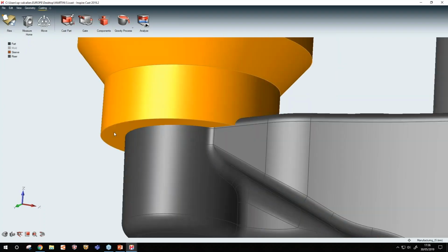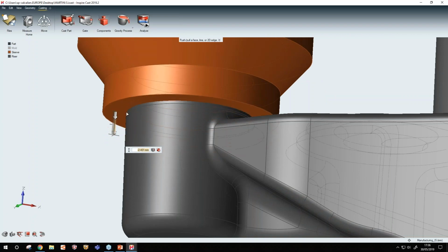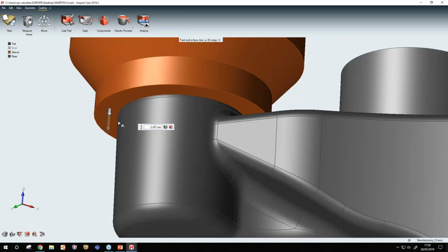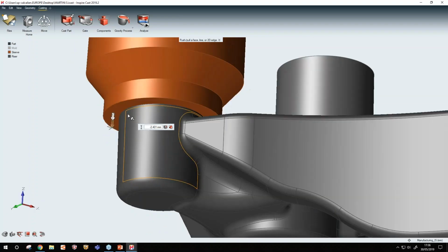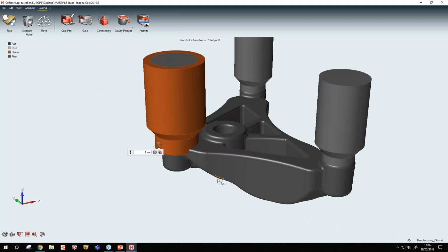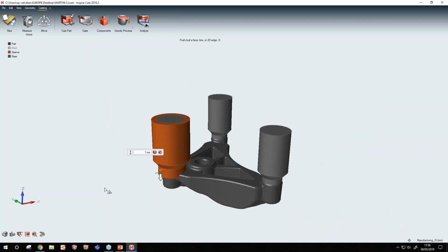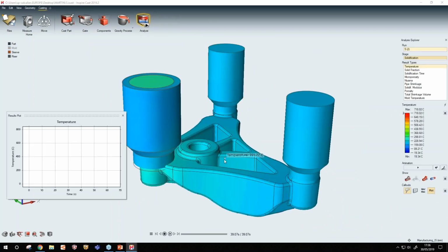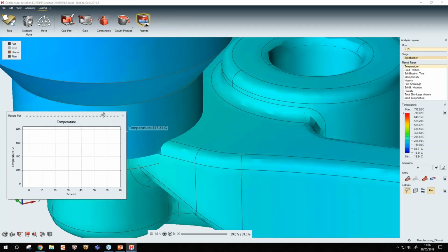You can always modify the geometry of the sleeve by double clicking on this surface and push-pull this surface. But in case you generate the sleeve automatically, internally and before mesh, we will take care of this. So if we go to post-process here, we automatically perform booleans.